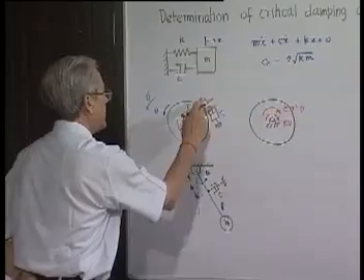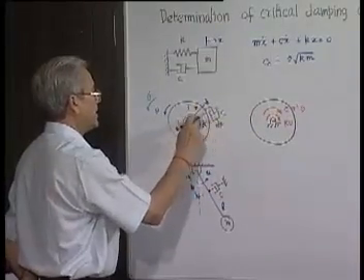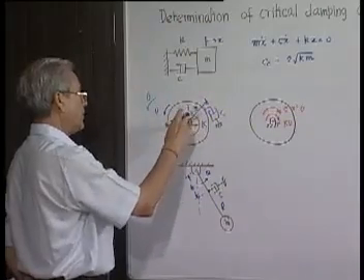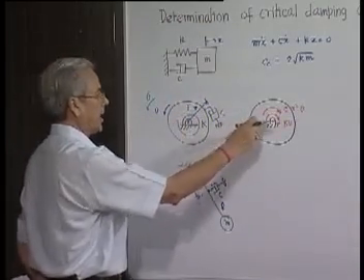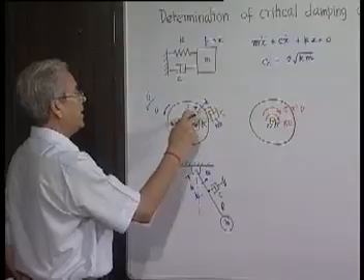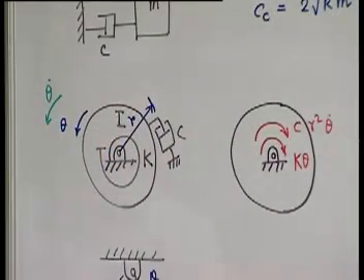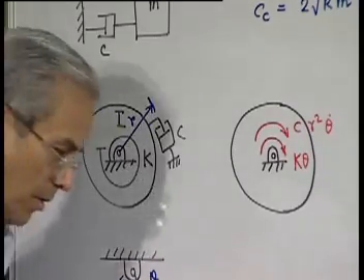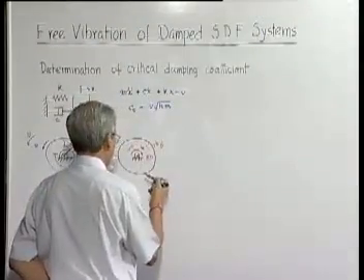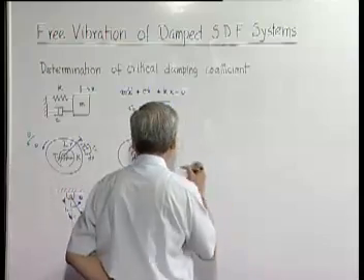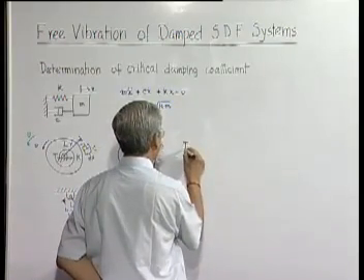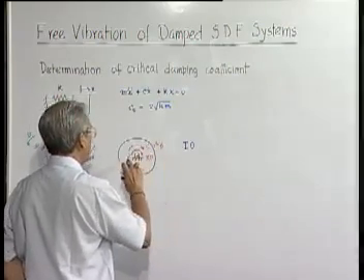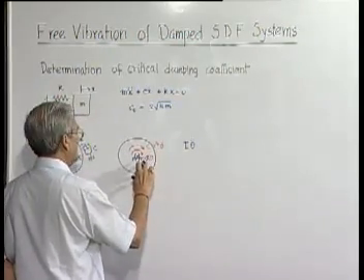That means the force generated is the velocity here, that is r into theta dot into c, and the torque or moment of that force, because you are writing only a moment equation, will be multiplied by this arm, and that is again r, which therefore makes it this. So, the equation of motion we get is I theta double dot in this direction is equal to minus this plus or minus this.